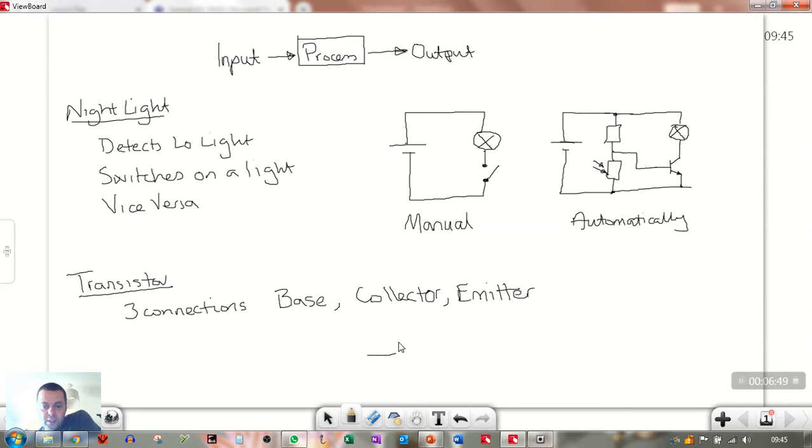Okay, so on the transistor, we draw that symbol. I want you to get used to seeing the symbol drawn because I want you to draw it. Right, the arrow pointing out the way. This one's the base, this one's the collector, and this one's the emitter. Okay. When you explain the operation of this transistor, you should be saying things like: when base voltage goes high, right?